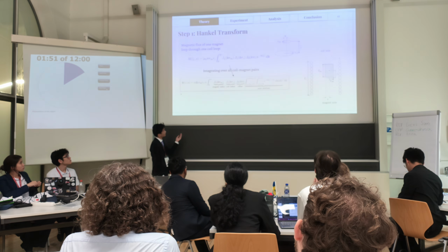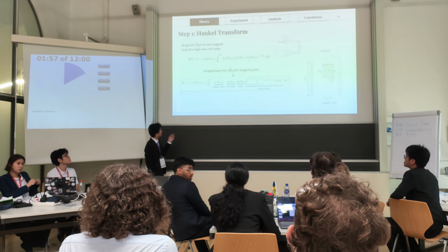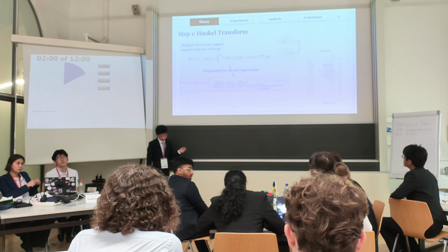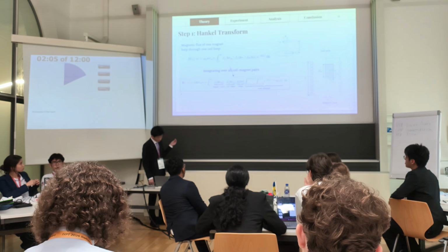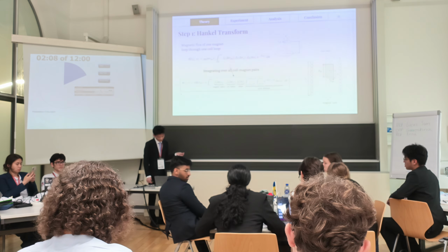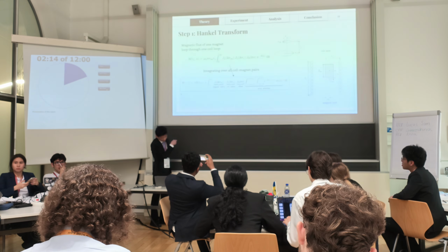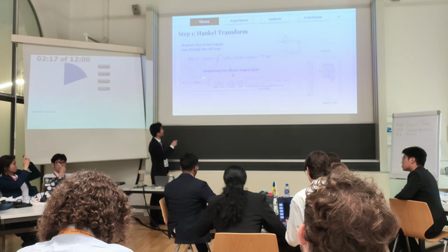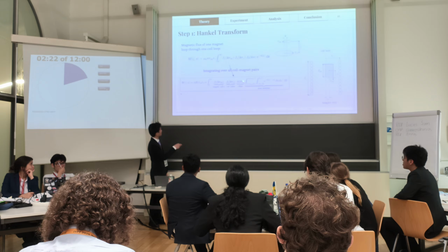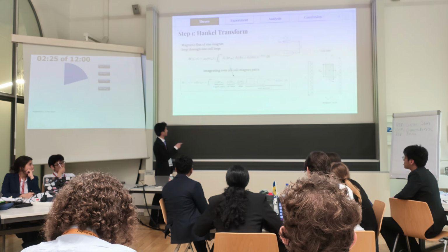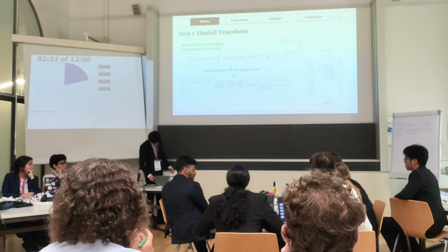The first step is that we do not treat the magnet as a point dipole, and instead we treat it as a uniformly magnetized cylinder, which is equivalent to a sheet of azimuthal surface current. We calculate the mutual flux between one magnet loop and one coil loop, which gives us this Hankel transformed expression. Then after we integrate over all magnet loop pairs, this is how we obtain the closed form distribution of the flux. And this is where the offset enters through a zeroth order delta function.